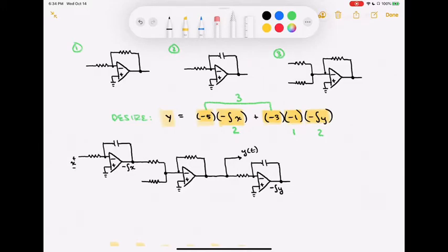So I'm going to go ahead and grab my gain circuit. So here's my gain circuit. Going to copy that out, place it in, and hook it up to that part where I just got my negative integral y. So I have something like that. That was the input into this guy. As long as I get my gains right, something so that I get a gain of 1, that means the feedback resistor is going to have to match the feed forward resistor. Let's go ahead and do that. Let's pick some realistic component values.